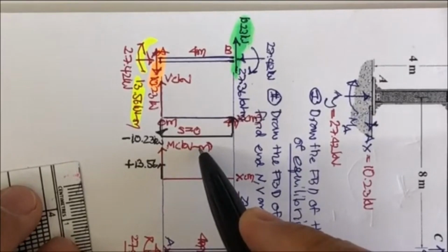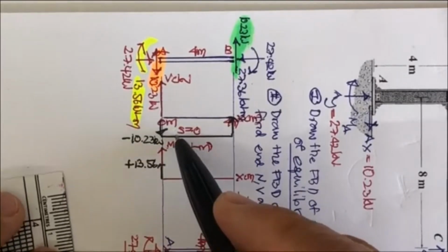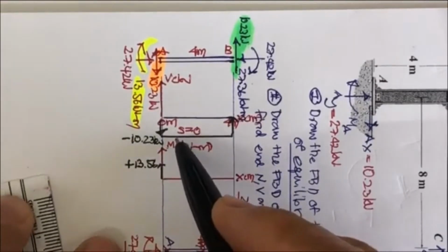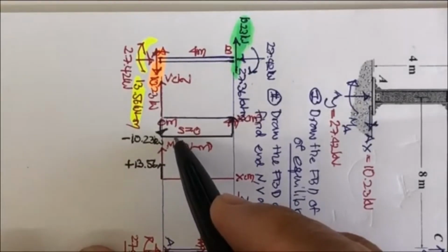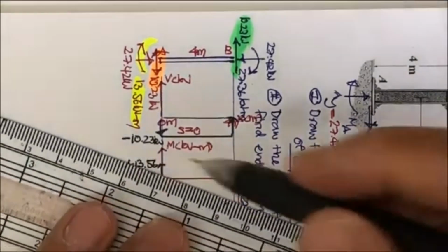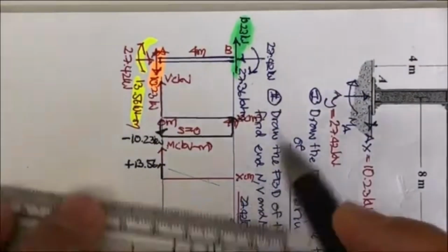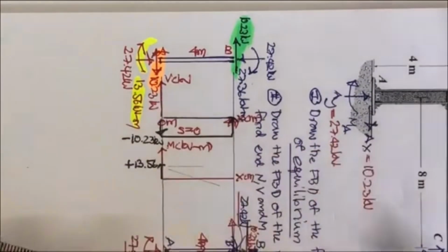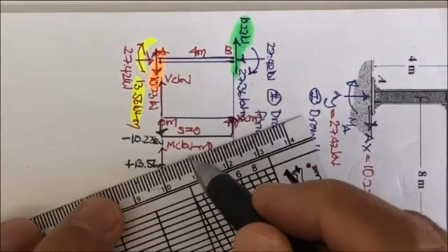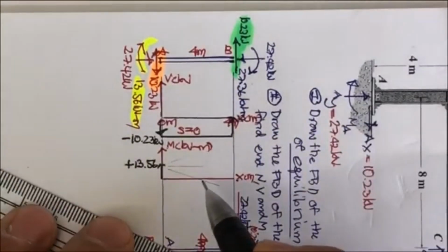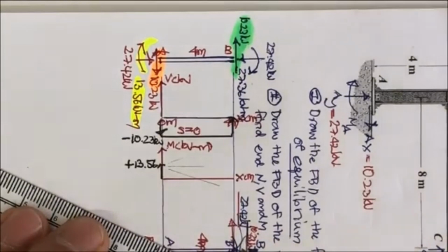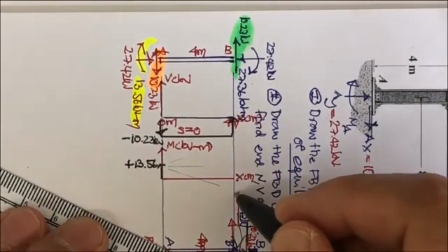And then what happens is you come over here, you draw the moment diagram, you take a look at the shear diagram, the shear is minus. So that means this one is going to have the curve like this. This is for minus slope. If the slope is 0, it is here. If the slope is positive, it's like this. This is minus. Okay. And you may wonder, this one is going to be what?